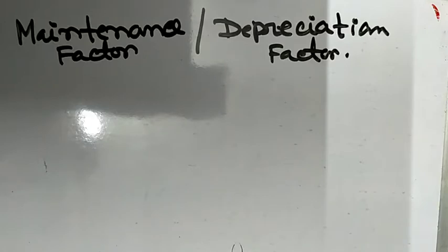Frequency of the cleaning schedule depends much upon the conditions prevalent in the particular industry. All the lamps and fittings are cleaned at least once in a year. However, if work carried out in the premises gives rise to dust or fluff, it may require cleaning of lamps more frequently. So, we can say depreciation factor